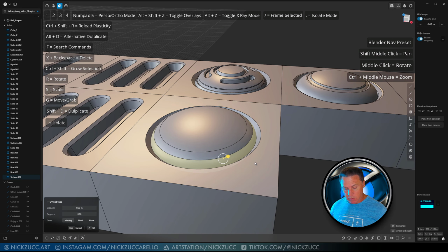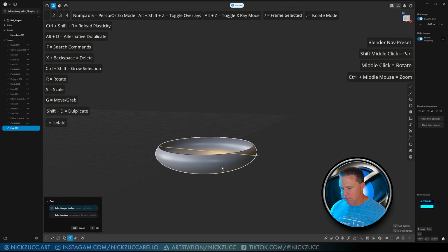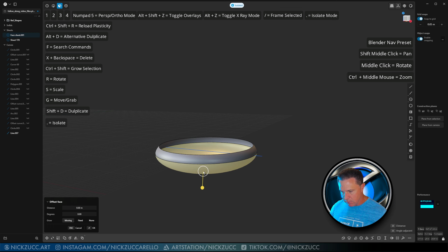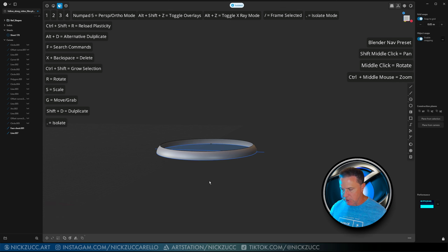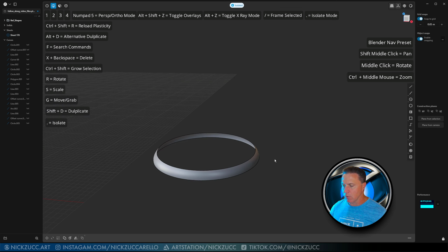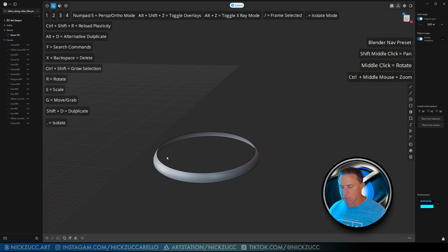Let's go back to our sheet and our curve. So I'm going to select those two, and I hit the period key. And then now I should be able to select the curve, tap 2, and I'll hit C to cut through it like that. And let's tap 3 right here for this face, and if we hit Shift X, it should get rid of it completely. We don't need this curve anymore. And now we've got this sheet body, or this sheet, correct?